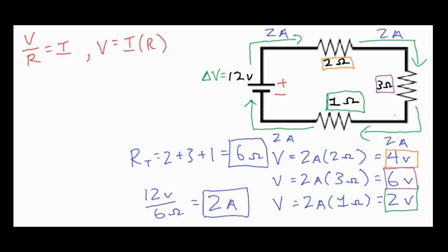All right, so I rearranged some things to clear up a little bit of space, but if you wanted to find the power output for any one of the resistors, and like I said, we'll just call them light bulbs, that would show you the brightness of the bulb. And you could find that a couple different ways. I would say the main formula that I typically use is IV, I being the current and V being the voltage. So it's kind of like the amount of charge that's flowing through, and then how much energy per charge is dropping through that particular bulb or resistor.